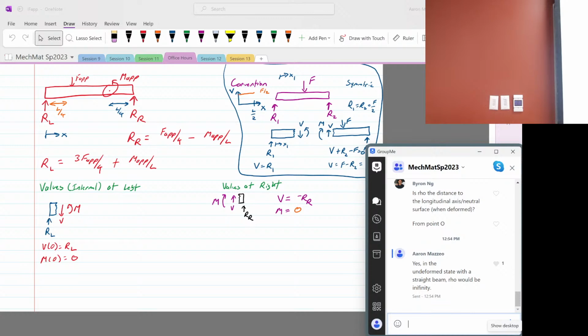What did you use for E and what is your nu? You had to put an E and a nu in the Primo Max, right? And what did you put in for E? No, E should be 200, right? That's what's important.